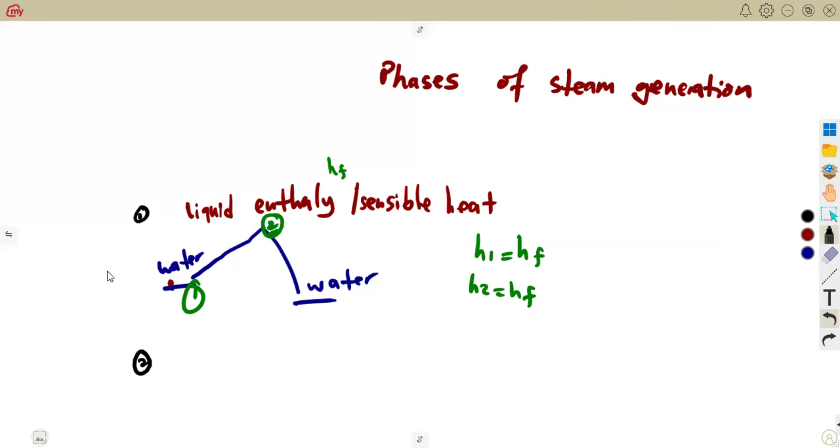So this was just a normal liquid or water, then we consider the steam, which is wet steam. From this second phase, the water is now heated up to where we can see the steam, and that will be wet. That is where we consider the latent heat, the enthalpy of evaporation, to be involved.